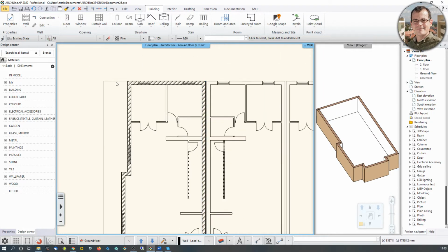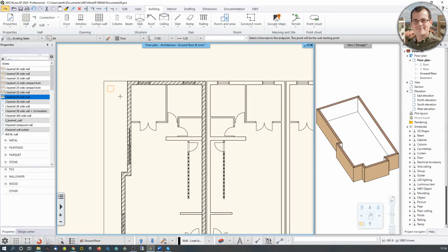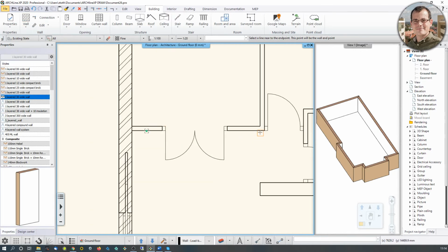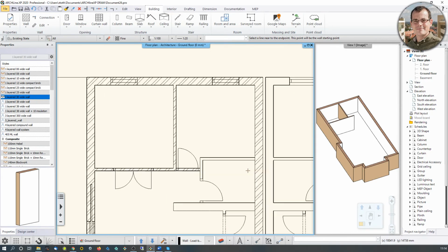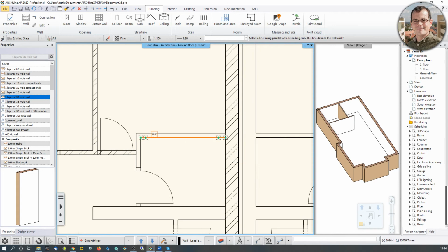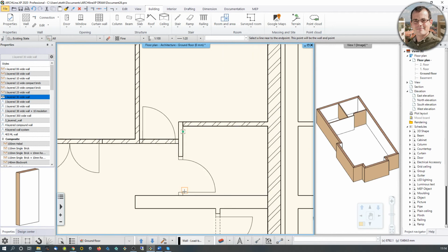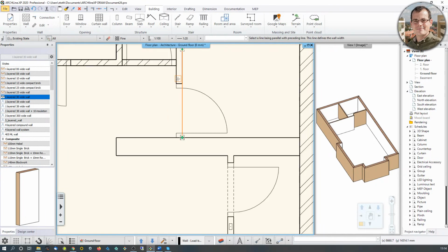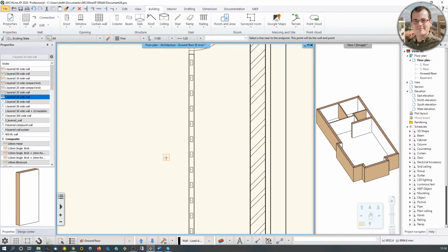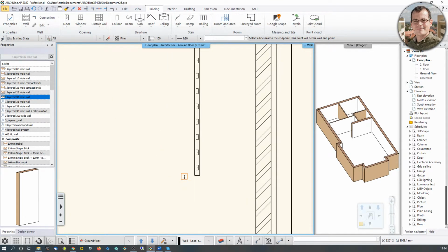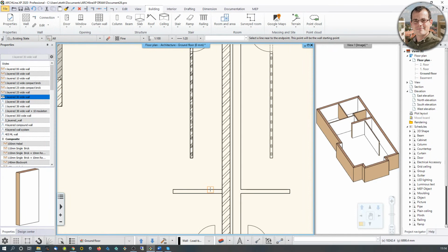Now let's go back to creating the walls. So I'm just going to hit walls in DWG. And you know the drill, just click on the opposite ends, opposite side, click on one, the other, and there you go. Obviously you could pick a wall with the corresponding thickness, which I think would be around 100 millimeters, but then you would need to change back and forth because the thickness is changing. So I think the best course of action here is just retrace what you see, and on the 2D you can see how it looks like.